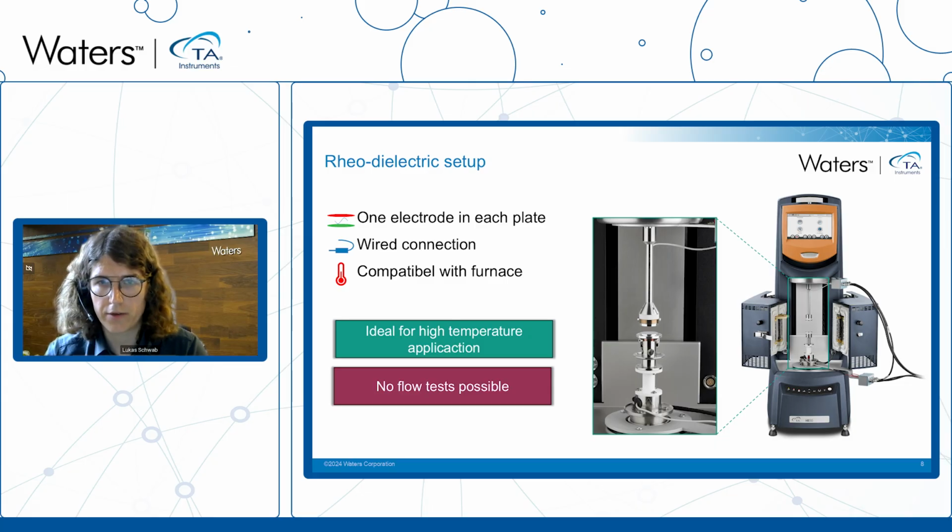So the advantage of this setup is that we have a plate-plate capacitor where we know all the electric fields very well. We have wired connections, which make for very good electrical measurements, so we can get very sensitive dielectric data. It is also compatible with the furnace in our case. So this is the ideal setup for testing dielectric properties, for example, of polymers at elevated temperatures under mechanical